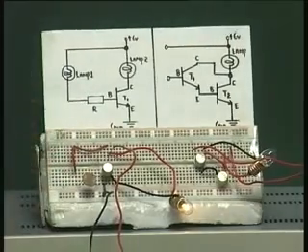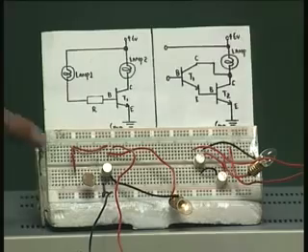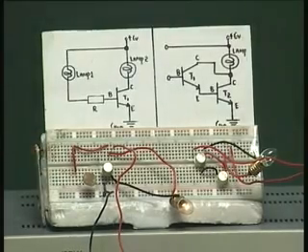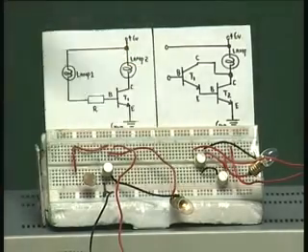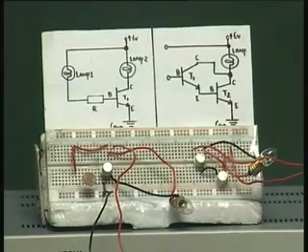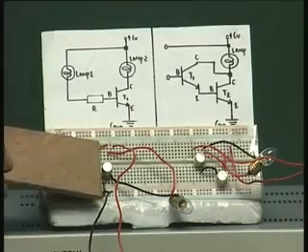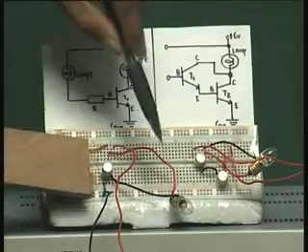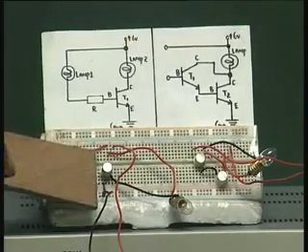Now this manual variation of the different resistors is brought about by using the light dependent resistor. You can see by changing the amount of light, there is enough light here which makes the resistance of the LDR, which is shown here, very, very small, and therefore you get a glow here. Now if I close it with some cardboard, you can see immediately the resistance increases, therefore the lamp is no more glowing. When I take it out, the lamp is glowing.